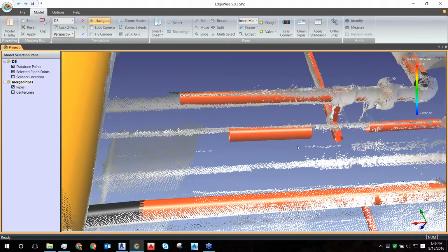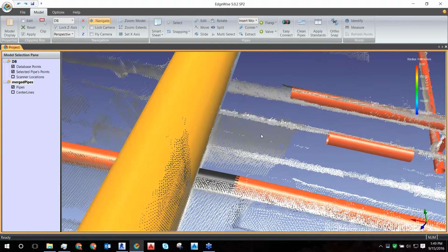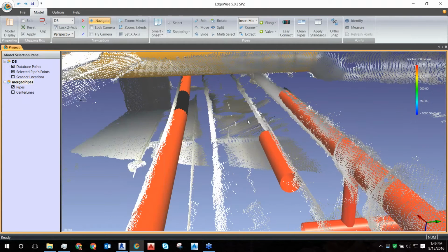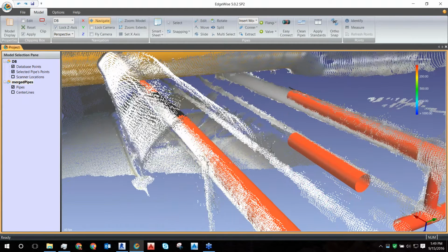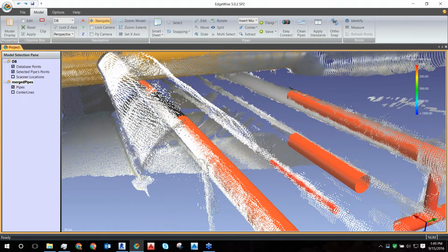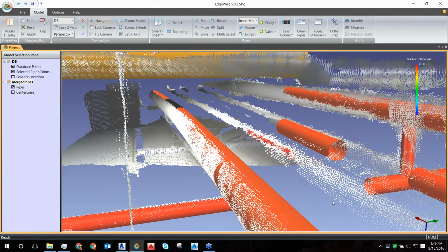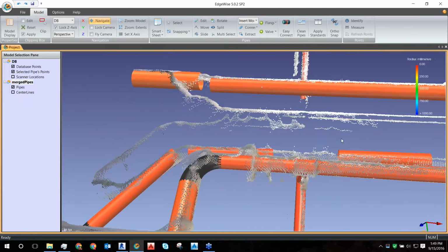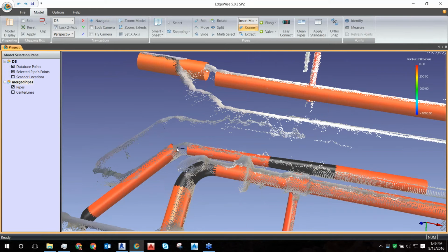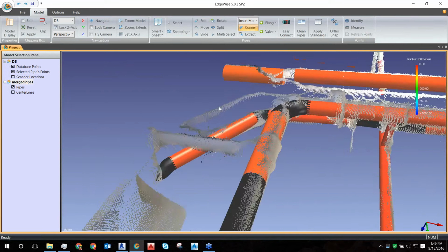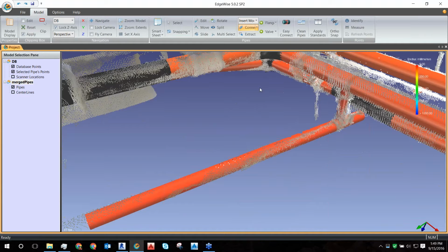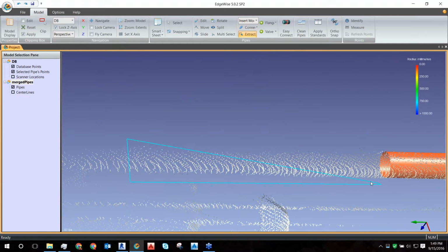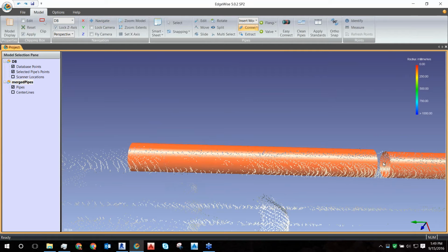What was the scanning rate that you used in this demo? So our device captures at 30 hertz, so 30 times a second we're capturing a frame of data. In the webinar, because we're sending this over a Wi-Fi link, we're broadcasting the contents of the screen at the same time as we're capturing them. That slows it down. It's probably only about 5 frames per second that you see, but the device itself is capturing 30 times a second. This drives how quickly you can walk through the scene.